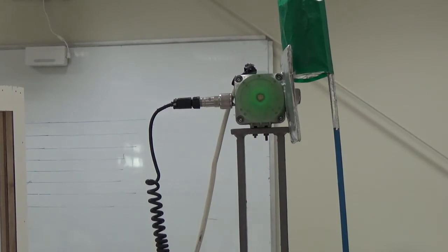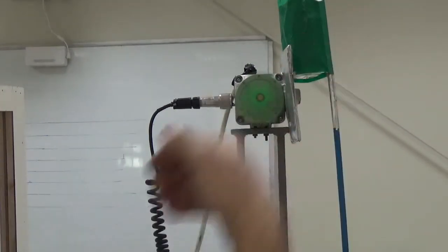Now what we will see in the spectrum is the frequency which will be equal to RPM multiplied by number of blades, and this will be blade pass frequency, and it will tell us that the problem is that blades are touching the cover plate same as before, but now in this case the amplitude will be more. Why will it be more? Because the blades are touching with more pressure, because I have pushed this one to this side, so there is more pressure.